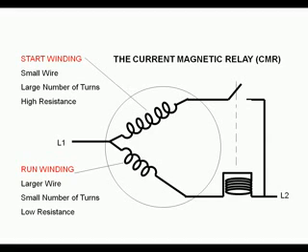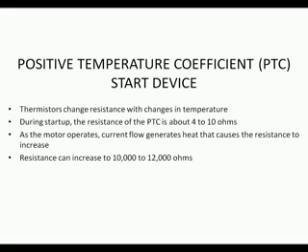As the amperage drops, the relay coil becomes de-energized, or should I say de-amperaged, because the amperage is what changes, and the relay contacts open. This is one of the few instances where you will see a coil, which is a load, in series with another load.